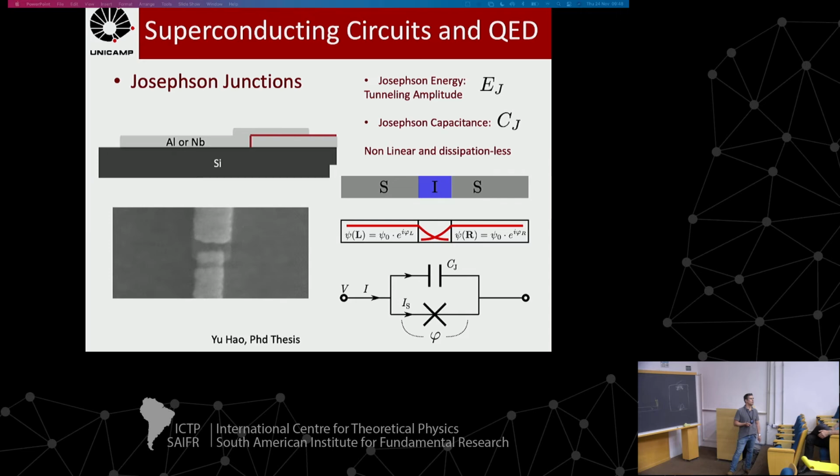I have a comment with respect to this sputtering process, because as I remember, in the sputtering process, when you have these aluminum particles moving, they are going in different directions. Not in this case. You would need a collimation, but we don't need it in this kind of setup. This is something like 1 centimeter here, and this here is like 1.5 meters. So when the atoms arrive here, they are basically in a straight line. It's like the sun to us. So the way to avoid that is with the distance.